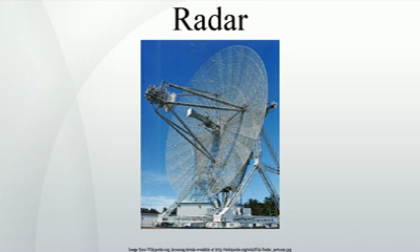Some clutter may also be caused by a long radar waveguide between the radar transceiver and the antenna. In a typical planned position indicator, PPI, radar with a rotating antenna, this will usually be seen as a sun, or sunburst in the center of the display as the receiver responds to echoes from dust particles and misguided RF in the waveguide.